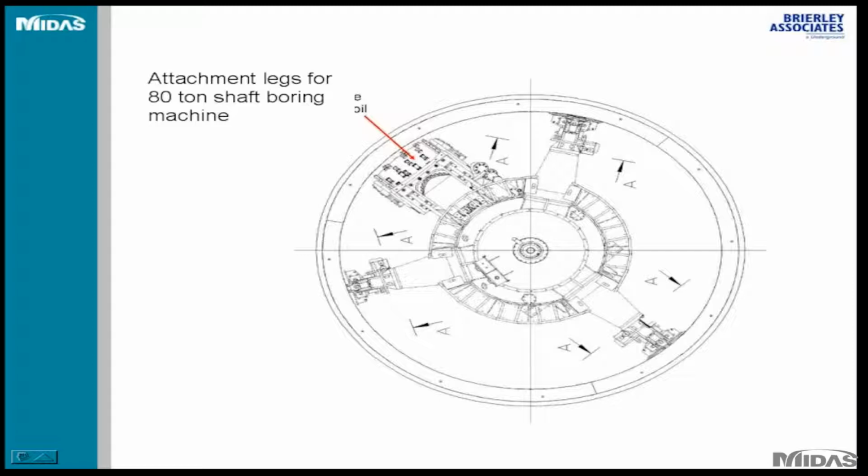Is it easy to facilitate an opening to connect your other structure? Yes, actually this system doesn't interfere with any subsequent construction. If you start the breakthrough process, it doesn't really interfere. Once you are done, you remove everything. You take the shaft boring machine out and remove everything, and in fact at the very end you cut the strands which suspend the shaft in place.